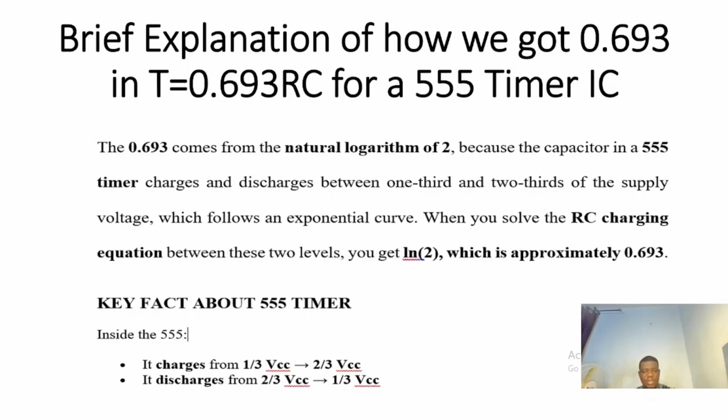Other facts you need to know from what you have there: it charges from 1/3. The common voltage we supply is VCC, but I just want to tell you that for the IC, go to the data sheet. So one thing is that any IC you want to use, go to the data sheet. You can also use 5 volts to work your design. Like the video you saw in the demo, the welcome design, I used 5 volts. I wanted to elaborate the explanation, so you now know that you are not restricted to just 12 volts.